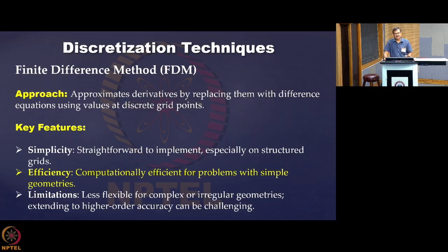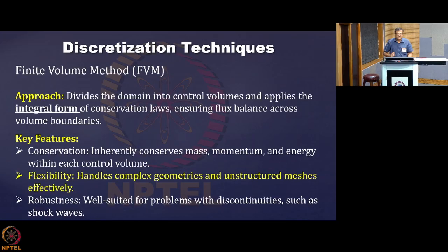So I now come to the other one, the finite volume technique. Here the domain is divided into control volumes, and the integral form of the conservation laws, which I have underlined and highlighted, whatever you have got in those fluid equations, you need to integrate over the volume.